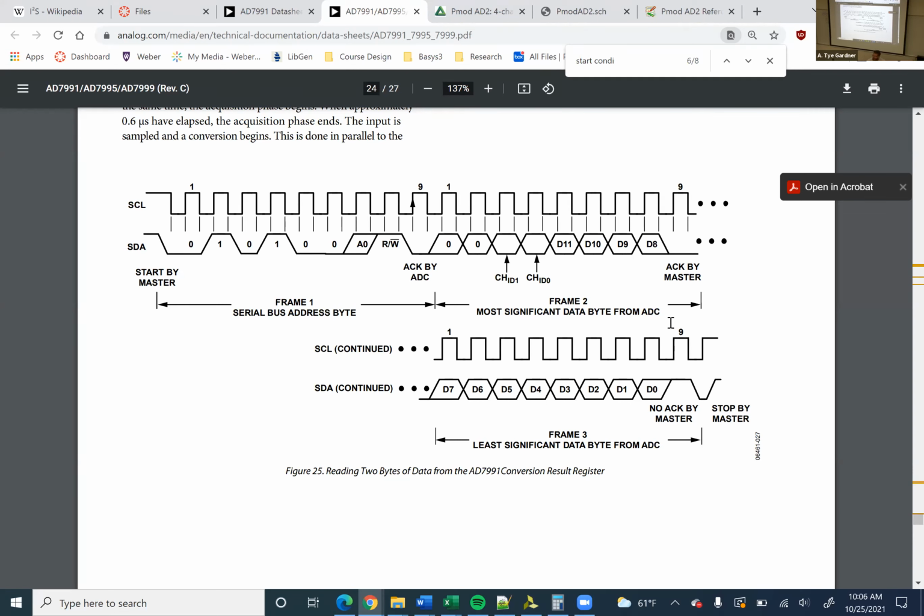There is a lot more overhead for this than there is for SPI, right? Because SPI can be very simple. There's no address. In fact, you can imagine SPI where there's not even configuration. You could have a no overhead SPI realistically. You can't have no overhead I2C.